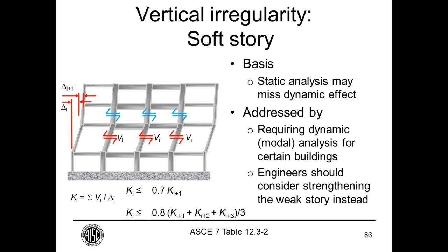All right. Our next question is getting into the irregularity portion of the presentation, and it was specifically on slides 86 and 87. So the question is, could you explain a little bit more? If we have more or less than 0.7 the stiffness compared to the next story, is it correct or not? So are we looking to have less or more stiffness than this 0.7 limit of the story above?